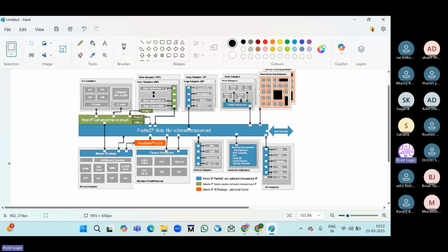So if you observe here, it's a system on chip design. System on chip design, in the sense, contains all functional blocks, whatever different types of architectures we are using in a mobile phone or laptop. If you observe the olden computers, we have the motherboards. Motherboard in the sense where we have a PCB board and we put all the components on a single board. Nowadays everything is system on chip design. On a single chip, we integrate all the different functional building blocks. That's what we call a system on chip design.